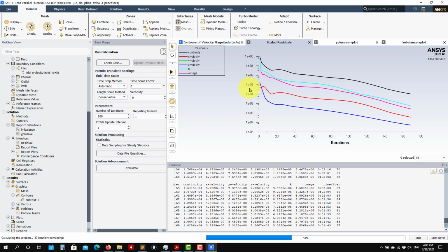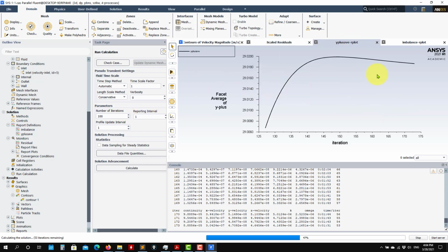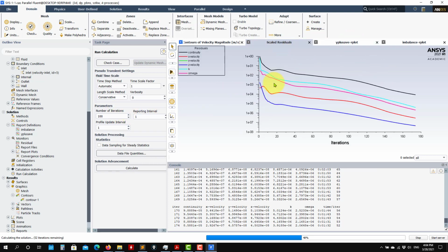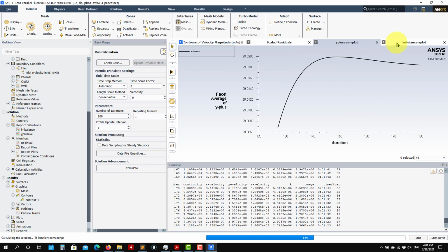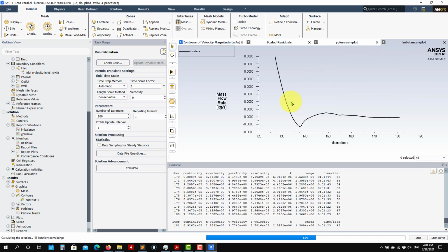We switch off this tolerance value, and then we let it run to the maximum number of iterations to see what happens. But again, this is not a direct indication. It is a good indicator, a good metric, but do not rely 100% on this. Always check some other metrics that might tell you more about what is going on in your simulation.